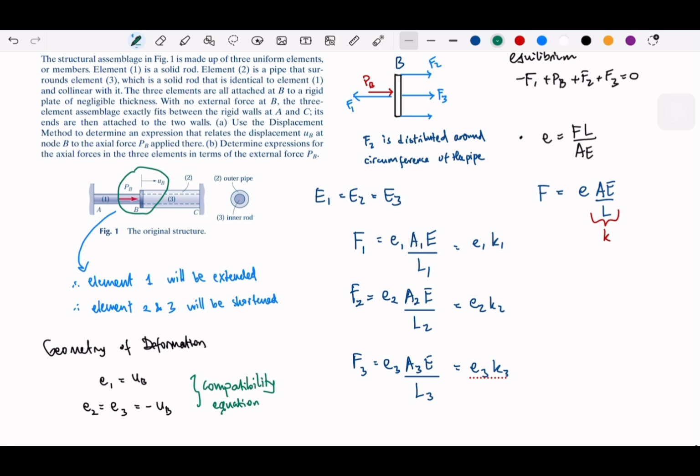The difference between indeterminate and determinate is whether we have this solution or this. If you see the forces, you see the elongations. If we do not set this up, we are not going to be able to solve these. So we need to set up the compatibility equations. That is how we see it. So if you have a problem, you have the equilibrium, all the things you can write, but you cannot find exactly the answer, then you need to have another equation to solve.